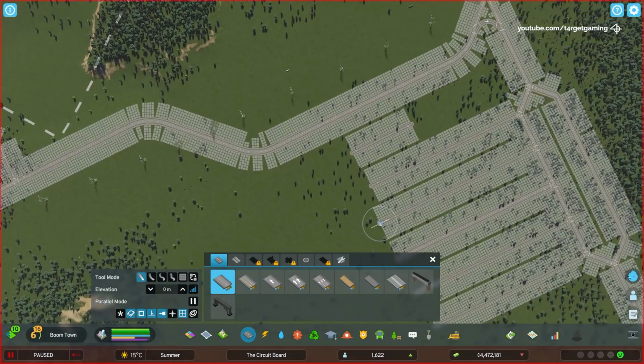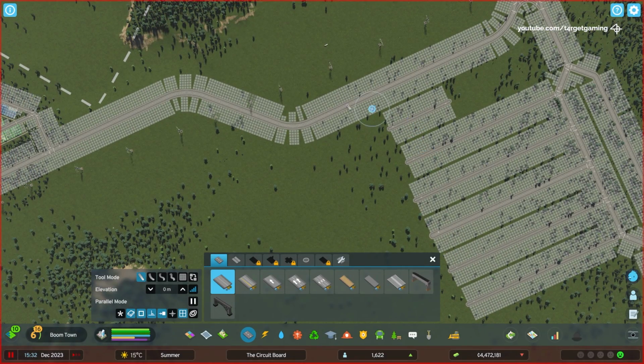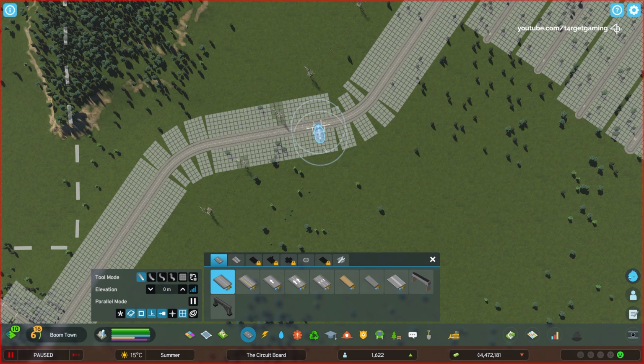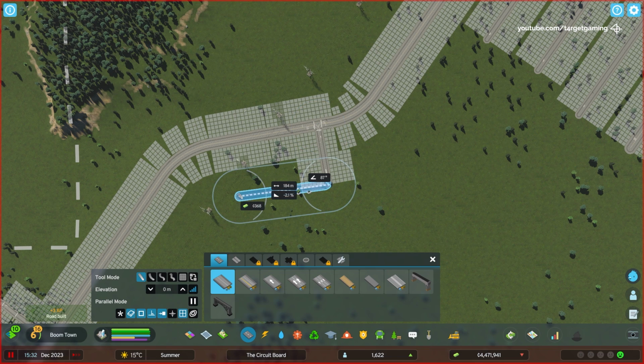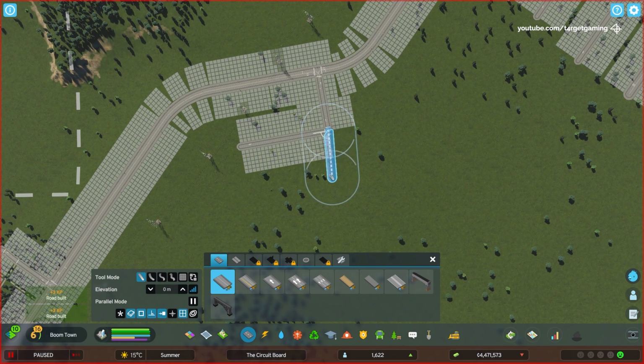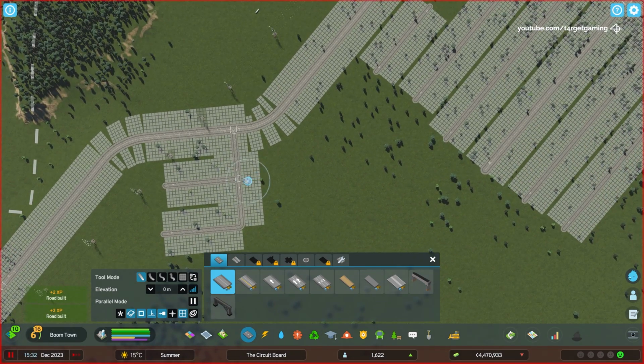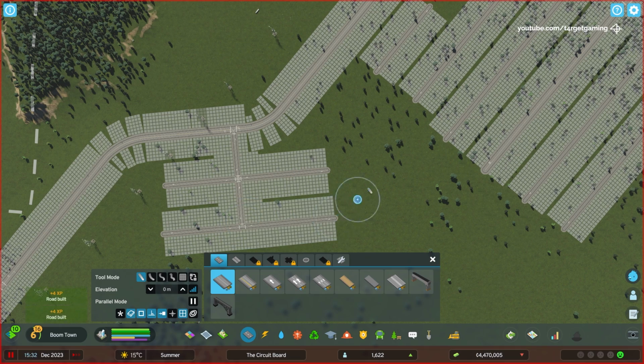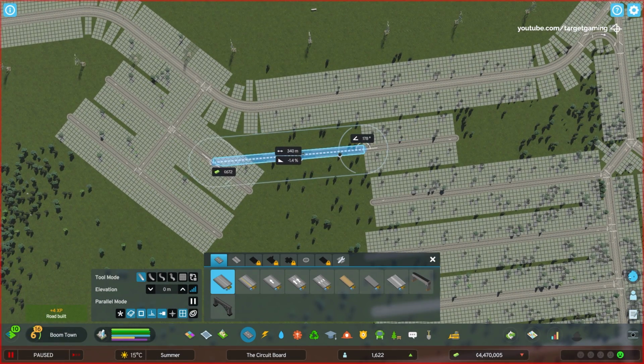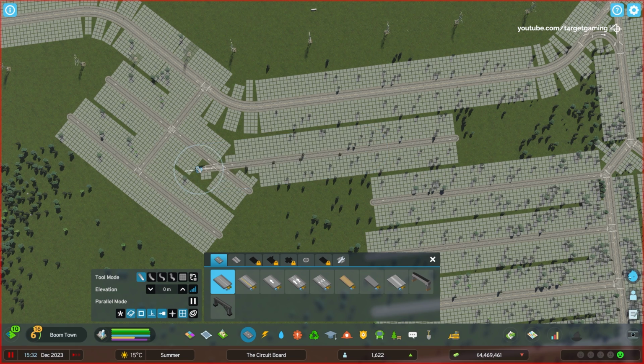For the street extensions, namely these 2 streets, which are going to turn around at the same orientation of the highway, so they're going to follow along, I can simply make a connection here at 120 meters, make a couple of roads, like so, and I'll just extend them, both of them, and where they intersect with this one, that's where we are going to make the connecting point.